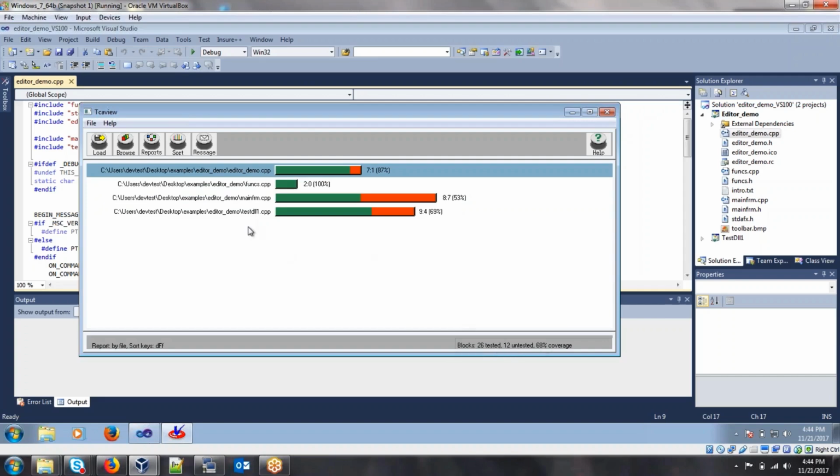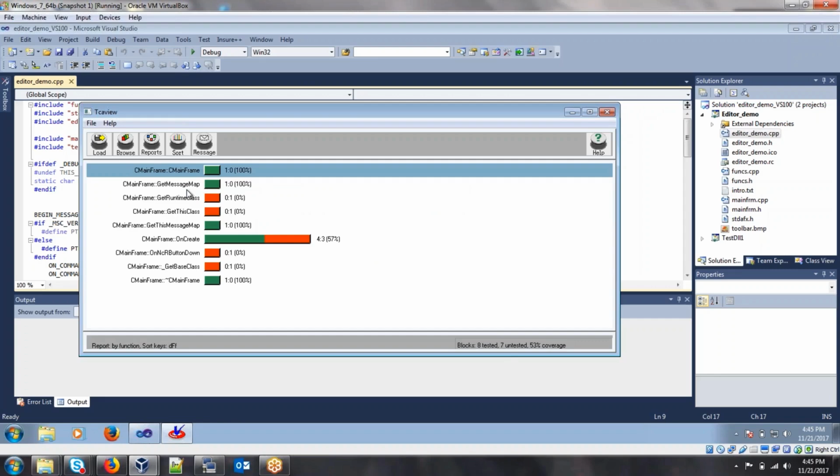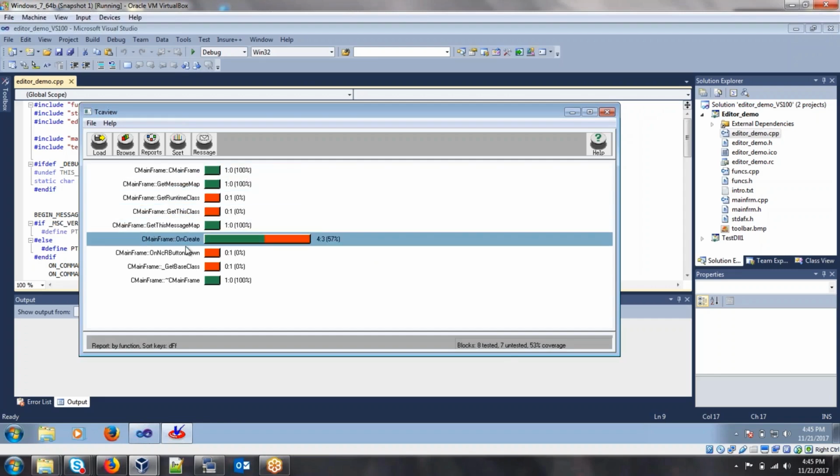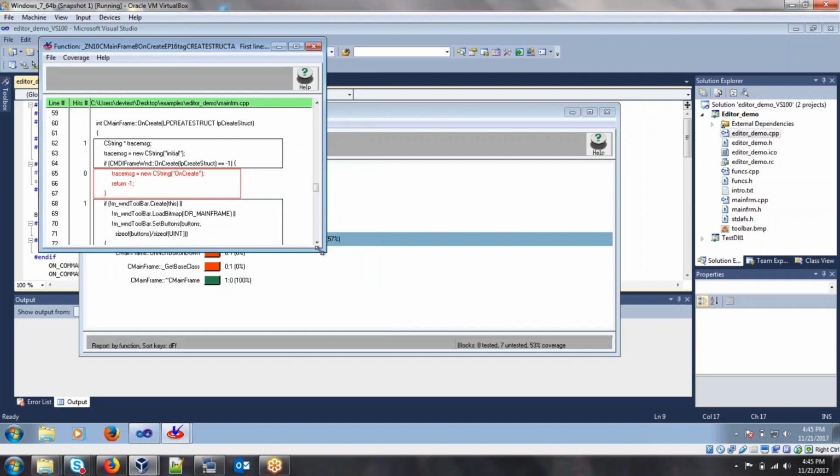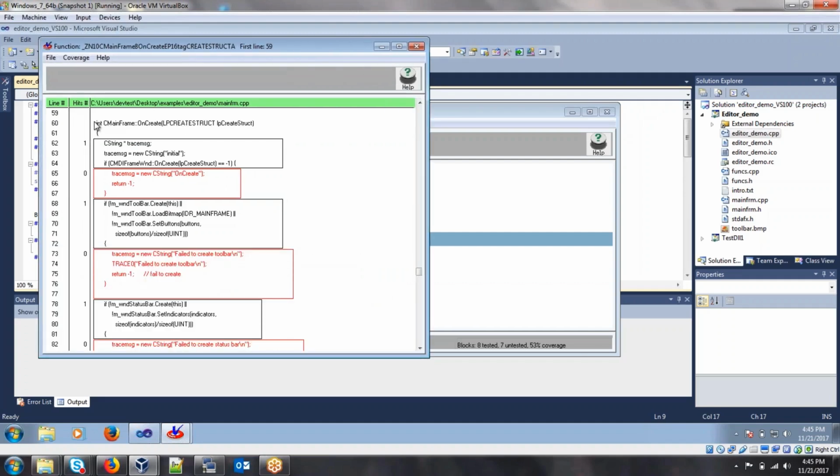percentage of that coverage. So drilling down further, it actually tells us now at a function level what blocks were covered. And browsing it further, it'll actually bring up the source code and show us in a nice block of what blocks were covered. The 1 and the hits over here determine if this was covered, and the 0 determines, as also shown in red, that this was not covered.